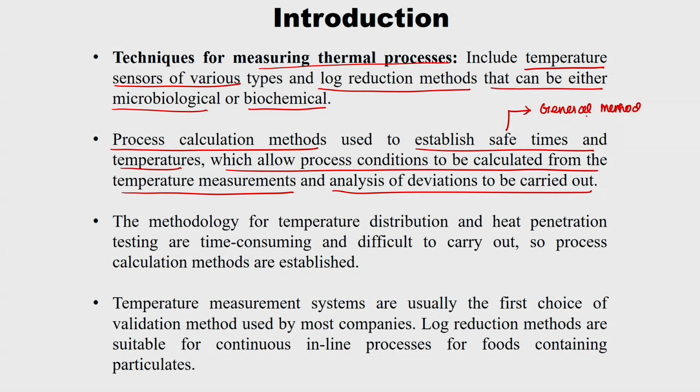Whatever time temperature combination you calculate goes directly into the lethality rate calculation, which is nothing but 10 to the power of (T minus T reference) upon Z. So, this T is a function of time, so that you calculate directly using the temperature sensor, substitute and calculate the lethality rate. From this your F value is established.